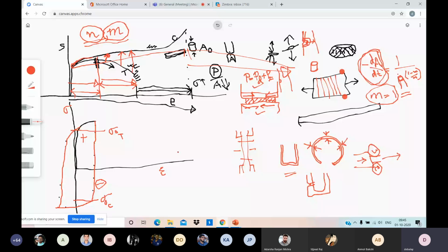But when you apply tension and then apply compression on the same material, you will find that the first time the yield strength that you get will be higher than the yield strength in the reverse loading. Which will be higher? The yield strength that you get in the subsequent tension. Have you heard this phenomenon before? Yes, sir.